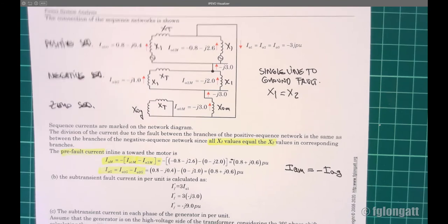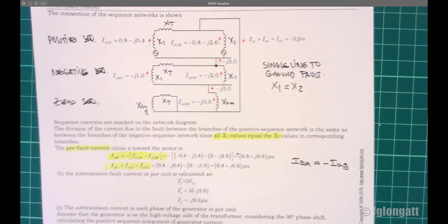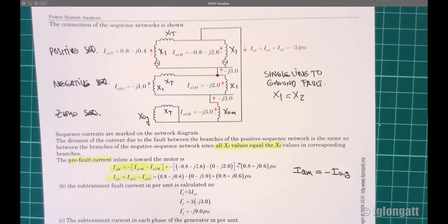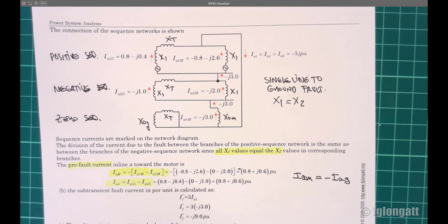Well, now that is totally clear the point, what we will do is, okay, let's calculate the single phase short circuit current. And to be honest, calculating the single phase short circuit current is something extremely simple, okay? Because you must remember that for a single fault current, the fault current is 3 times the positive sequence current, okay?